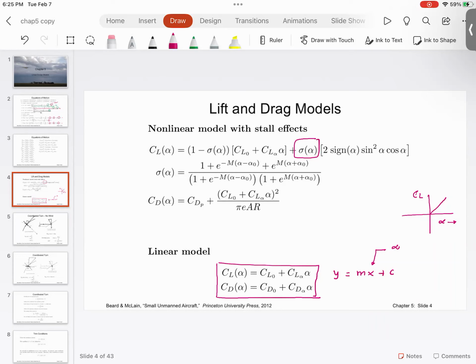You don't want that. We want that aircraft to continue to fly in a level flight, which means the aircraft must achieve the dynamic equilibrium where the aircraft is moving at steady velocity. Everyone understood this? That is the meaning of trimming.